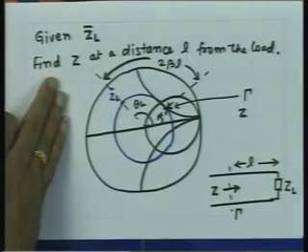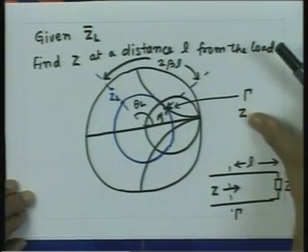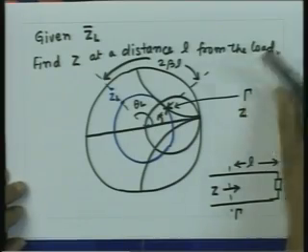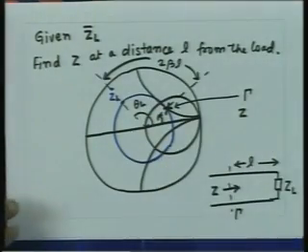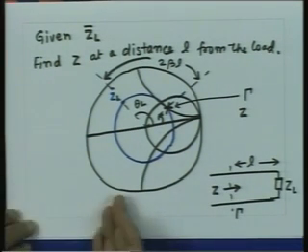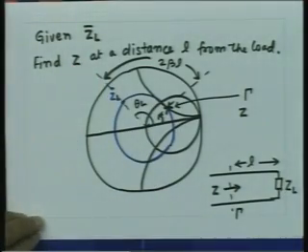If I now replace the impedances by the admittances, and I am not interested in the calculation of the reflection coefficient, but only in the transformed admittances, then the axis for the reflection coefficient does not come into the picture. So, the procedure for transforming the impedance and the admittance is exactly identical.